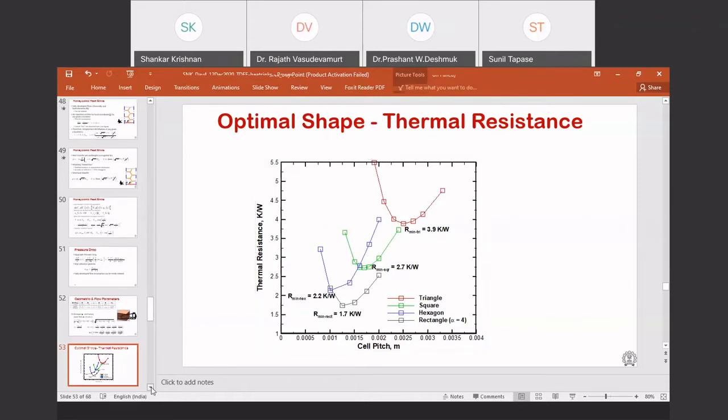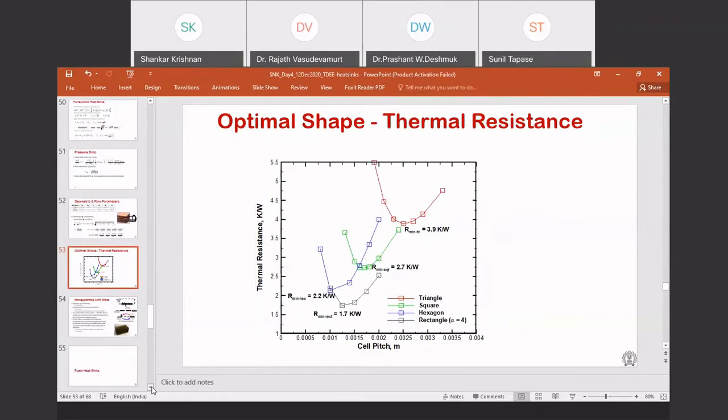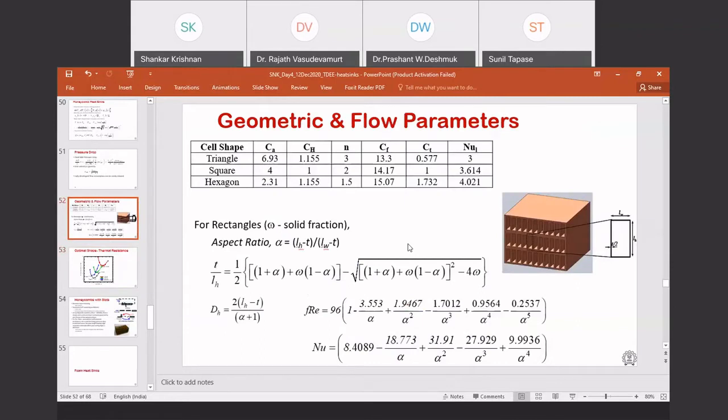So that is one example of hexagonal ducts. However, as I pointed out earlier, if I had my heater at the bottom here, these ducts get much hotter than the ducts that are on the top. Even if the fin efficiency is close to 90%, you still see that top ducts see much lower heat transfer compared to the bottom ducts. So it is better to mix them.